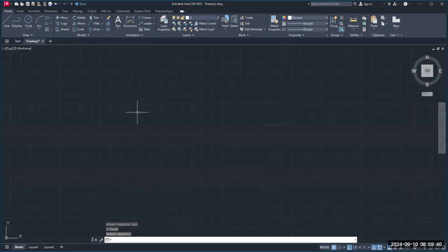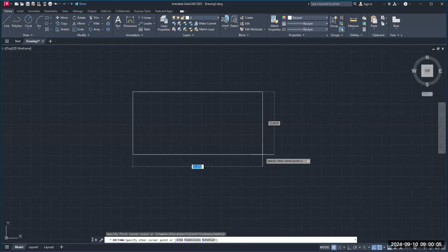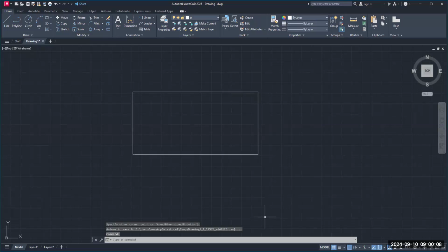So far today, we've learned line, polyline, circle, rectangle, polygon. We did move, copy, rotate, mirror, trim, fillet, erase. Okay, I'm going to show you explode. All right, go to rectangle here. Go to rectangle and draw just an ordinary rectangle. Click, and I don't care what your dimensions are. You could just click 2 points and you have a rectangle.